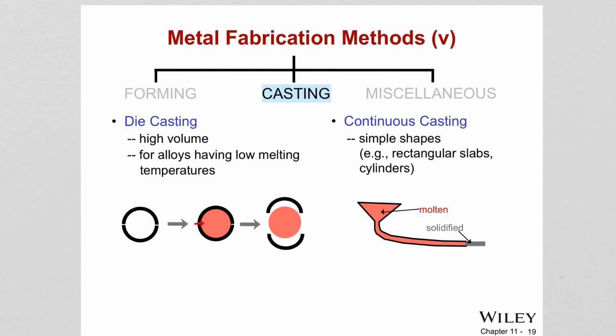The mold opens up and releases your part after the casting is done. This technique provides rapid casting rates because you can use the die again and again. You don't have to form it again like you do in sand casting, and this of course reduces the costs.